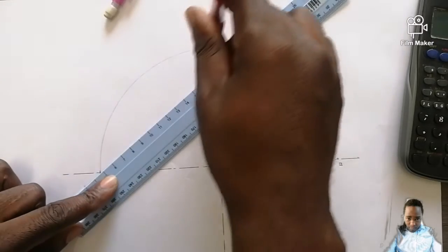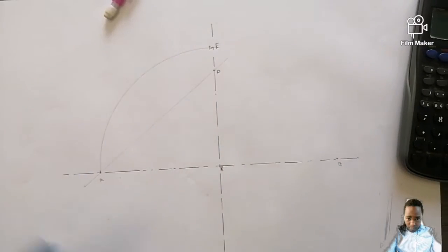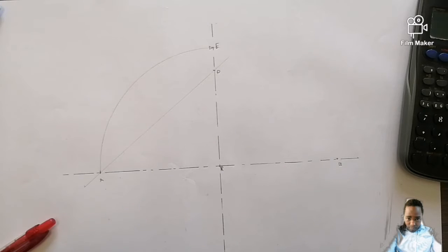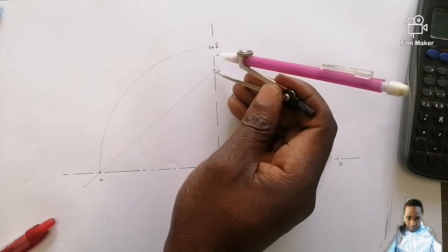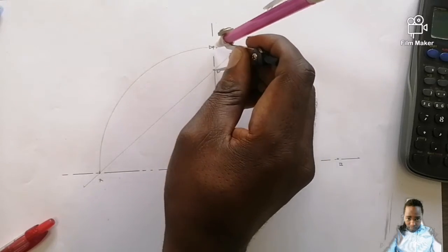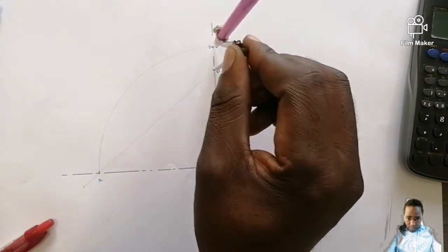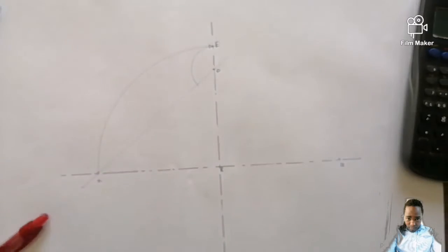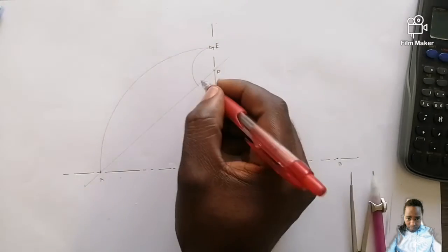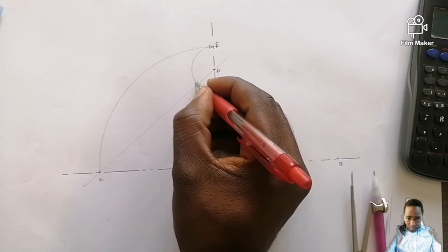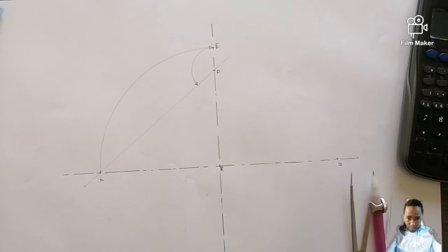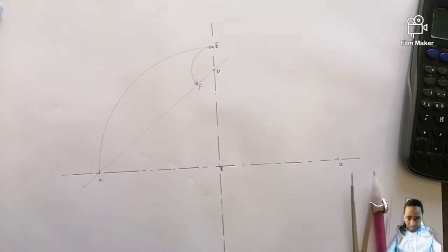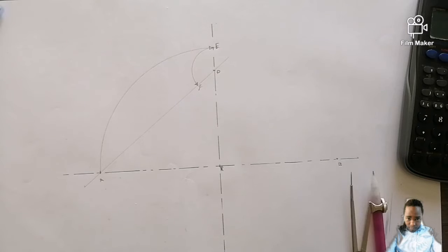Like this we go. Faint. Now take your drawing compass, put it at point D, further extend it to point E. This is it, and strike an arc that's going to be like this. Once it crosses the line of DA, indicate by an arrow again that you strike this arc going this direction, and this is going to be point F. You understand? This is going to be point F.